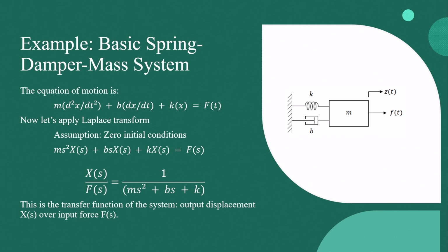In the same way, equal and opposite reaction will happen. So if we apply the Laplace transform to this first equation, the force equation, then we will get the complete equation in a Laplace transform, transfer function based equation itself. But before going to that, we need to have some assumptions. We need to take the initial conditions as zero, then only we can understand it as starting from the zero state onwards.